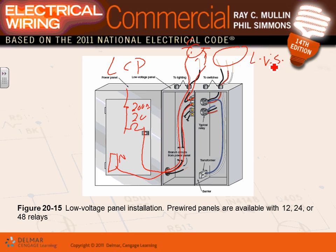This part is called the lighting control panel. You have designed this one, Adam, with your friend Chad, the lighting control panel. You have multiple relays, and you guys have installed the relays, right? I don't know how many relays you came up with, 24, 48 relays at once now. This is called the high voltage section of the relay. This is the low voltage section. What does that mean? This is all 24 volt. This is 120 volt or 277 volt. And they're separated by code. They have a barrier between them. You can't put the 24 volt and 120 in the same enclosure unless you have a barrier between them.